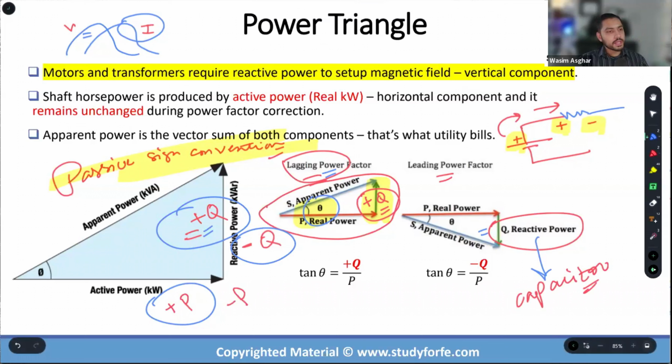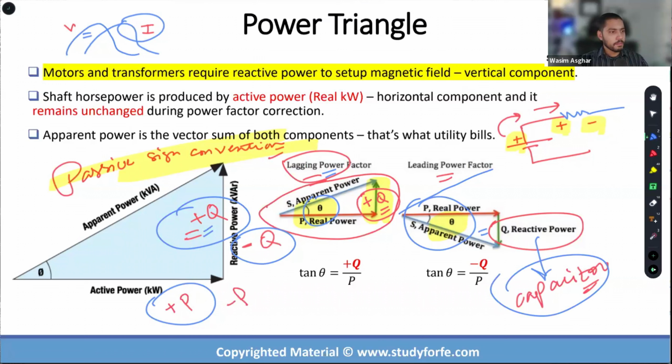So we have a load that is connected, which is overly capacitive in nature, with the Q pointing downwards. Just pay attention to the angle theta, how that behaves. It is also negative. This angle cannot point upwards if your Q is pointing downwards when you have an overall capacitive load. Does it make sense?